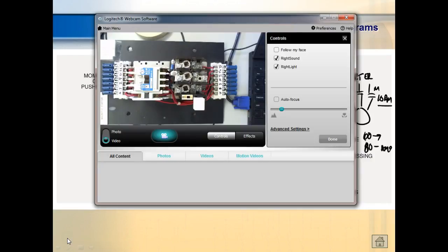That's what gets people confused, because you're not paying for voltage, you're not paying for current, you're paying for watts. So if I have something that's designed for high voltage and I put it on that high voltage, it's going to be cheaper to run because it's going to be 1800 watts at that voltage, right? You understand that? What it means is I can use smaller conductors to get that power out.